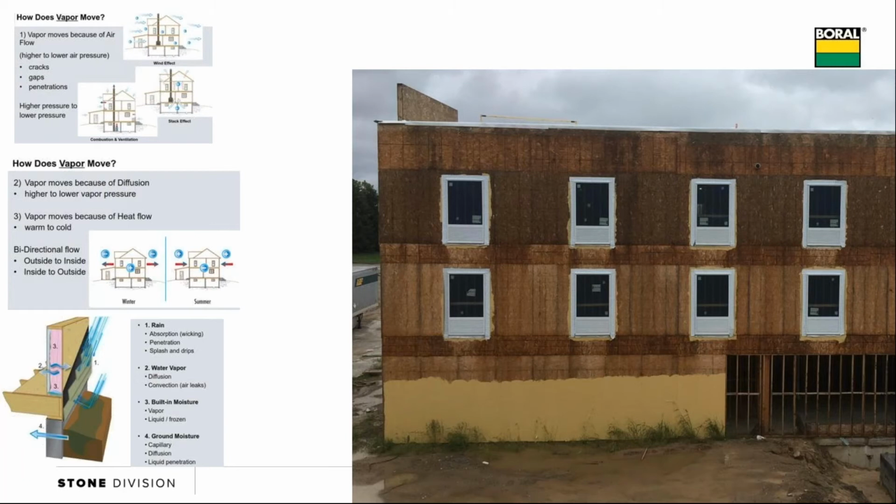Again, I'll suggest that pretty much all claddings leak. And I will tell you that manufactured stone is definitely not waterproof. It's the job of that primary WRB and the flashings and all those openings and penetrations. When those are done right, that's what keeps water out of that building. So I think to some degree, we as contractors need to get back to being those cranky masons and contractors who do a really good job of inspecting the project before we get started and going on record if something isn't right.